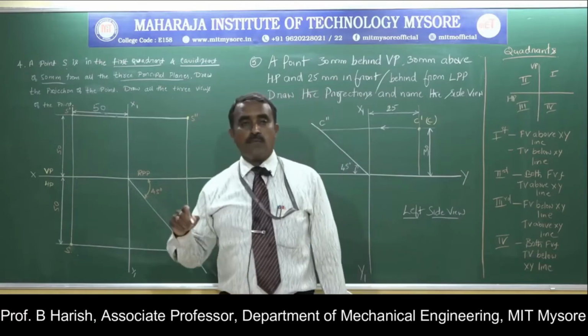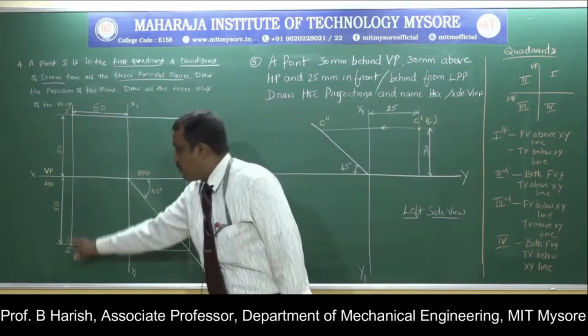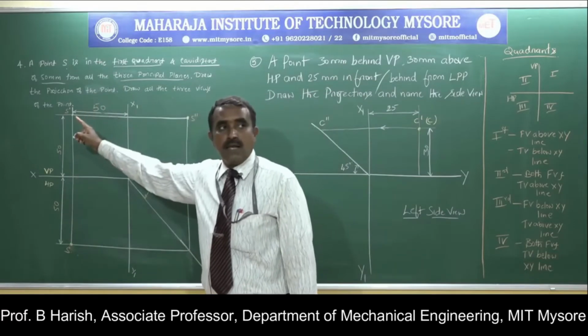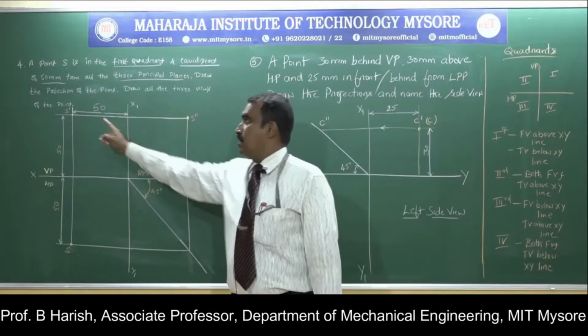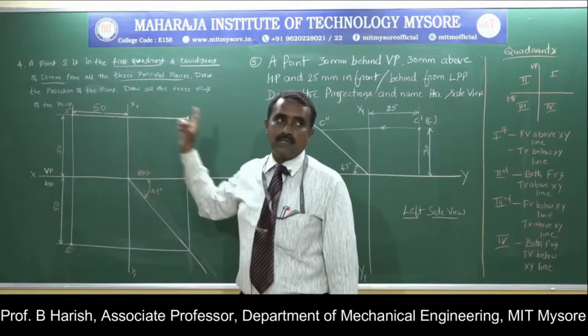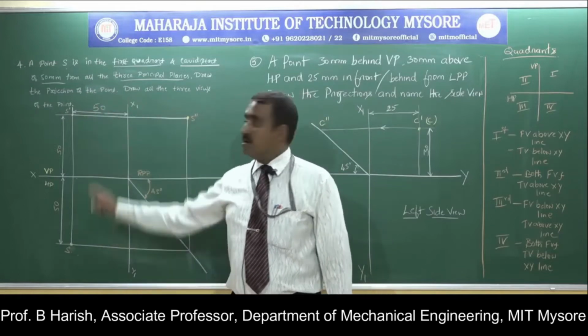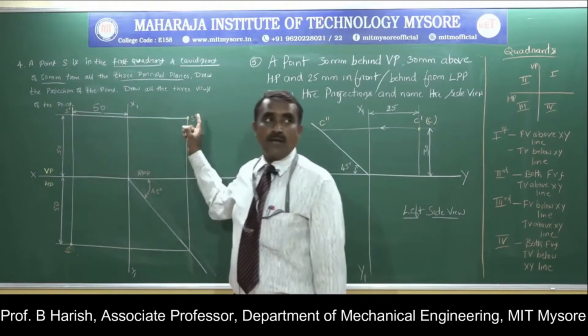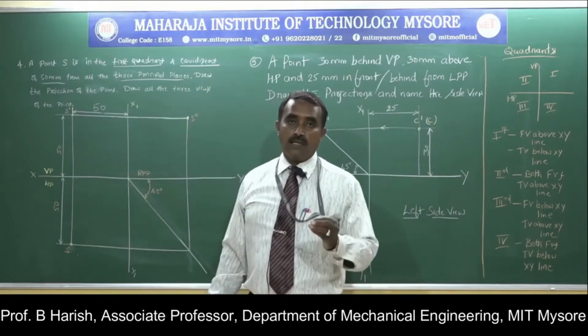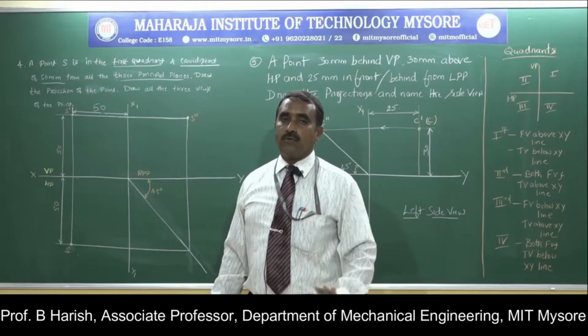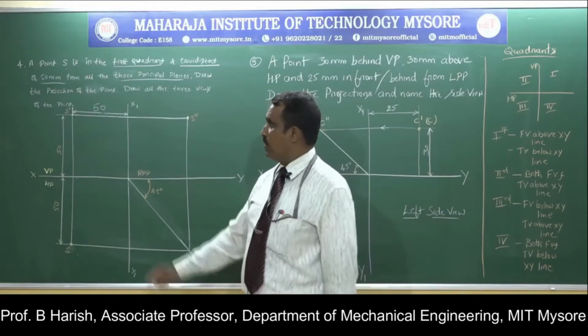One thing you have to remember: top and front view will always be in line. Similarly, the profile view and the front view will be in line. Always top and front view will be in line, and front view and profile view will be in line. That is the principle, that is fixed always. That point you should always remember.